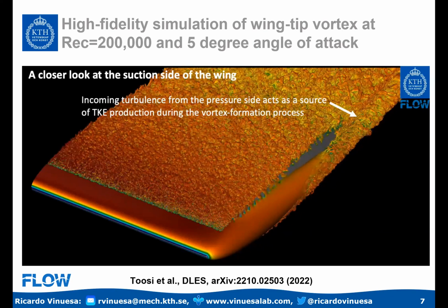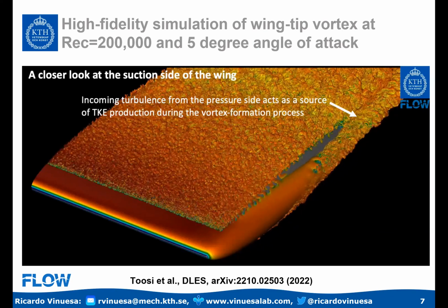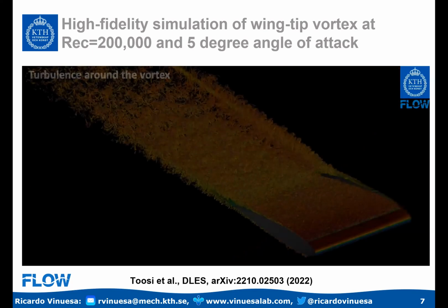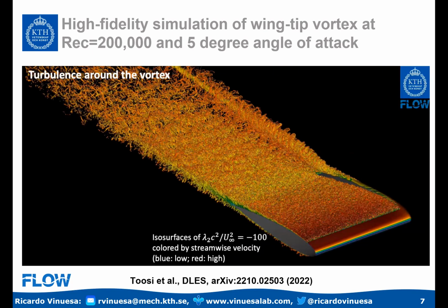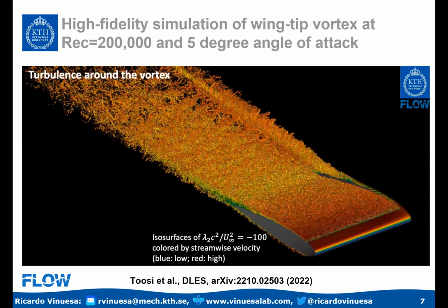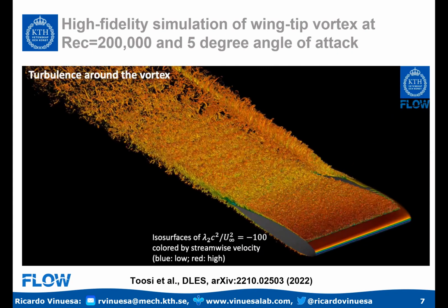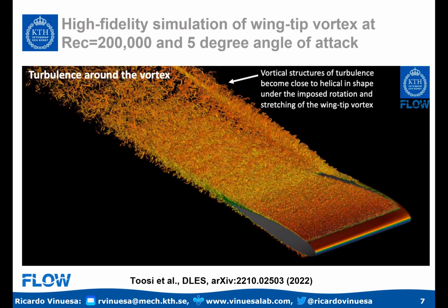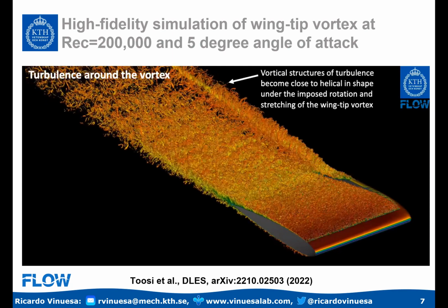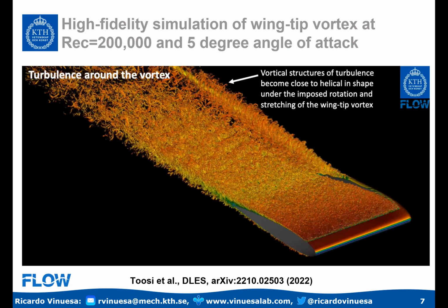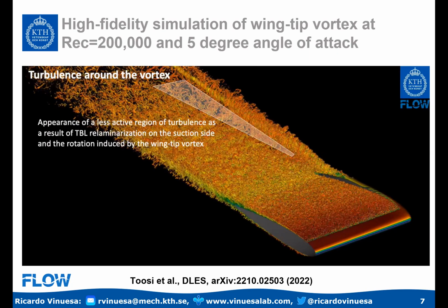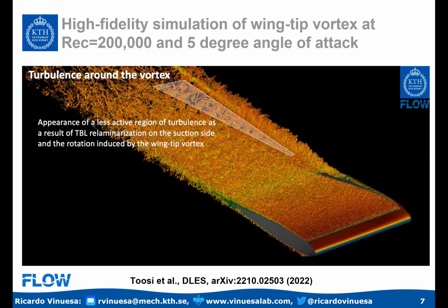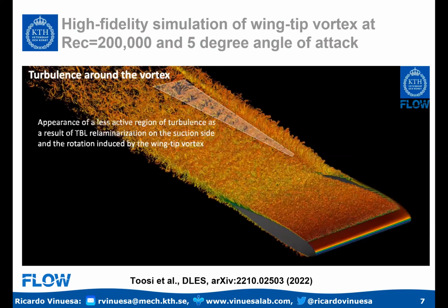But what is interesting is that the wingtip vortex produces a quite strong spanwise pressure gradient, which is relaminarizing the flow locally, as you can see now over here. And that's expected, no? Because favorable pressure gradients, acceleration of boundary layers, lead to possibly relaminarization, which is what we observe here. And this has a quite pronounced effect also in the wake. So the wake really sees how this attenuation of the turbulent fluctuations is affecting its streamwise development.